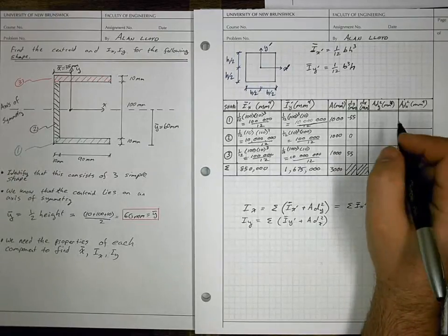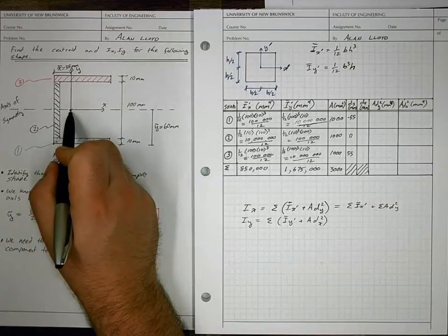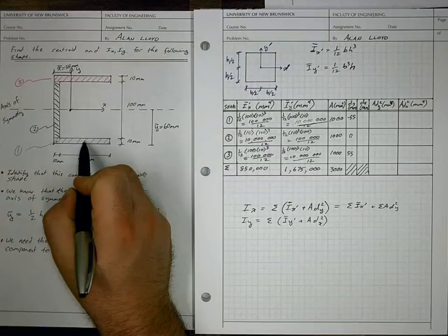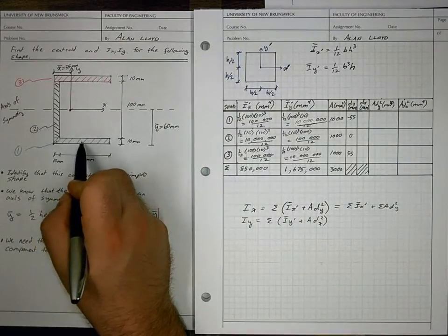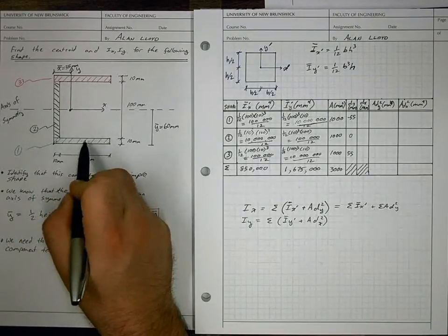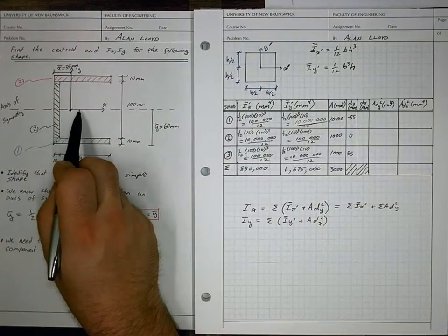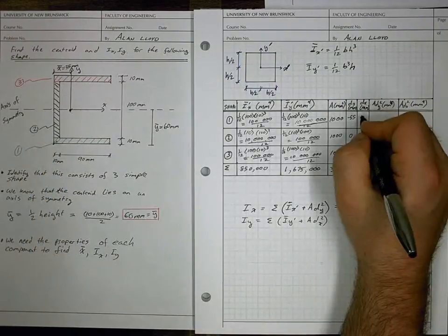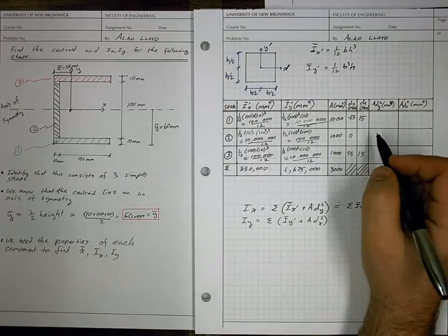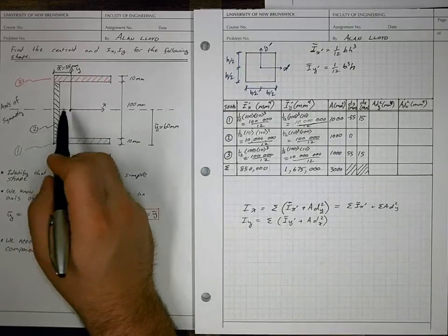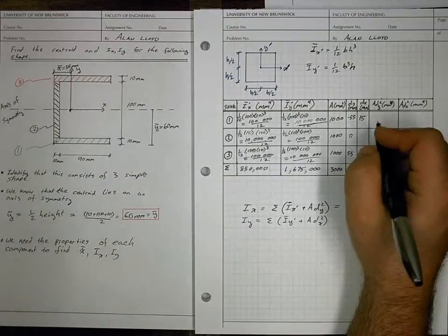And then the distance in the x direction, well, starting here, if we want to get to the centroid here, from here to here is 50, and from here to here is 35. That means from here to here is 15. And the same with component 3. Now the centroid to component 2 is going to be 35 over, and then coming back 5, so we will be at minus 30 here.